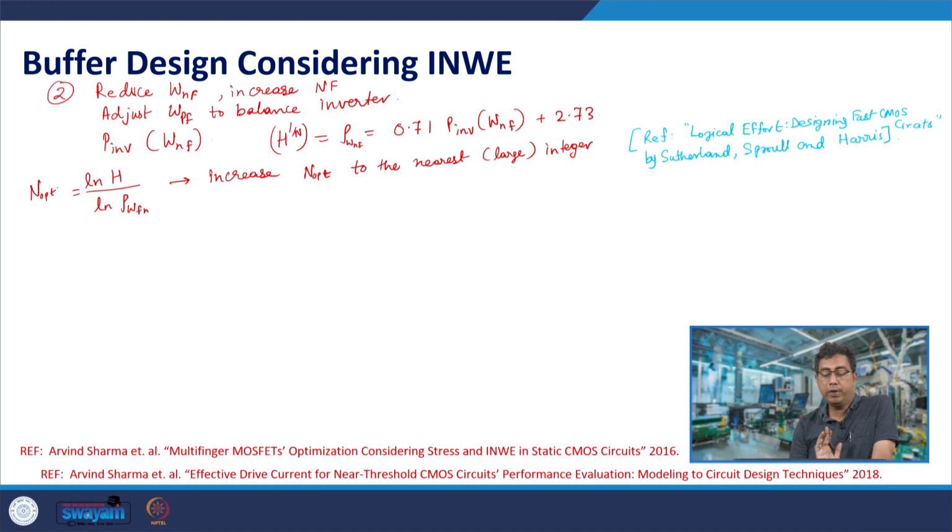Now, we discuss the energy. We know the leakage current per width of that device of the inverter. We can calculate the average I leakage of the P MOSFET and N MOSFET. So, E leakage we estimate as average I leakage times VDD times the delay of the buffer.